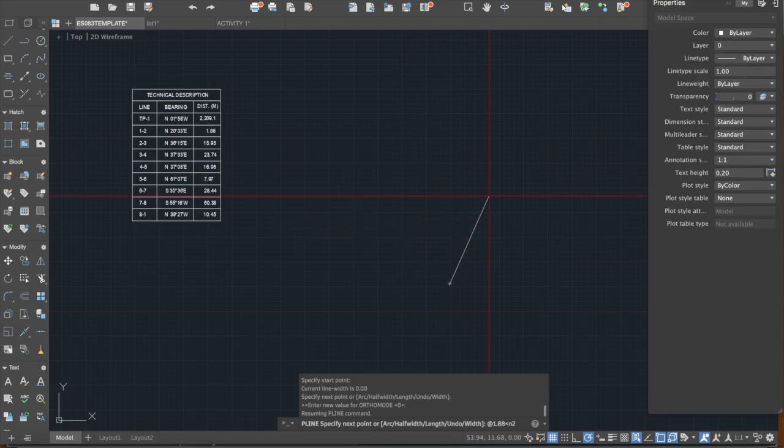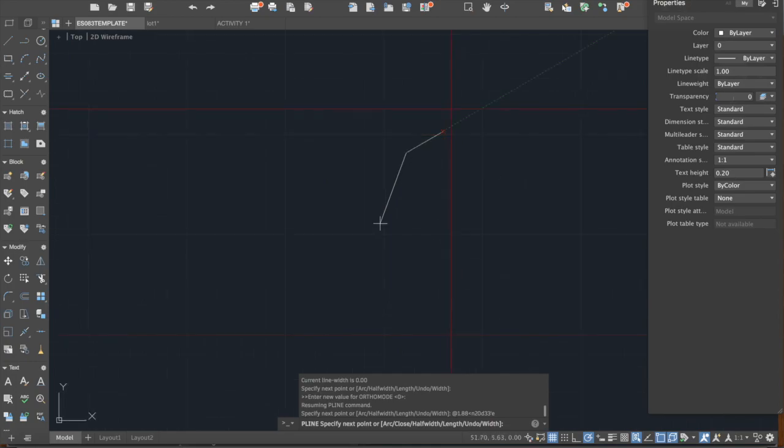So 20 degrees or 20 D. And then the minutes now is 33 minutes, and then that would be one apostrophe, and then the next direction, which is east. East, enter. So as you zoom in, this is where the next point is. So this is equivalent to point 2.